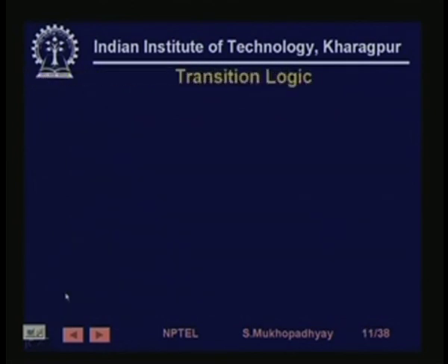Having done that, we can start developing our program. We have seen that as the system moves on, the various state logics and transition logics are alternately computed. First, there is a state in which some state logic will be satisfied, and depending on that, outputs will be exercised.